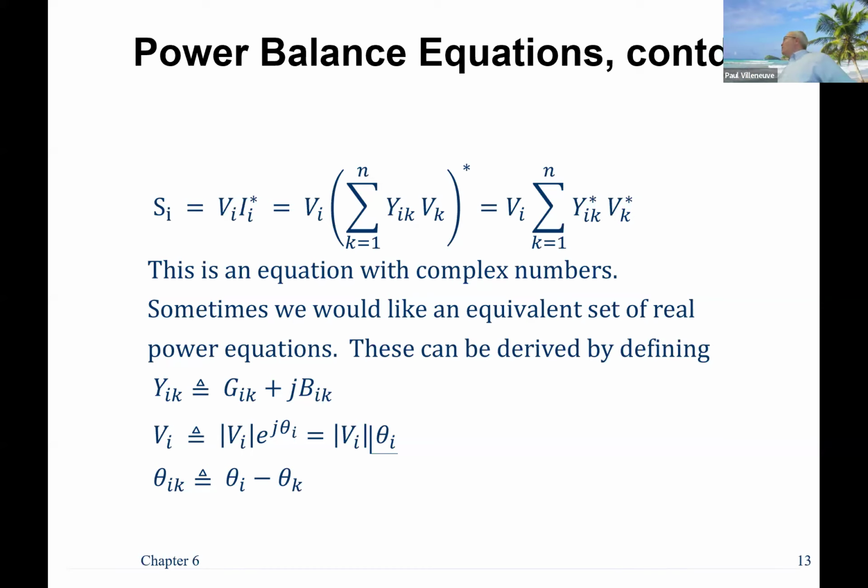So if you look at this equation over here, it's all based on voltages and Y bus. You're solving for the bus voltages, and you've calculated the Y bus initially. So if you can use your nonlinear equations to solve for the voltages, you have all the equations and all unknowns that you have. Now, here's the hard part about Newton-Raphson.